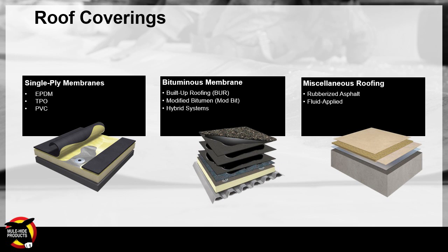And now, continuing with the roof coverings, the other common types are modified bitumen, which is that multi-ply system that we talked about. Hot tar is the evolution of that. It's evolved into rolls. So we sell both modified bitumen in a self-adhered version, which is peel and stick, very simple, seen in a lot of residential situations because it looks really nice, can match your shingles.